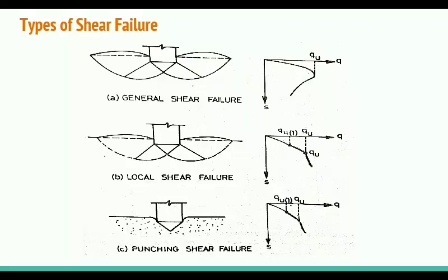In this case, the failure surface does not extend up to the ground surface. This happens when you apply the load on loose sand or soft clay. The failure surface cannot extend up to the ground surface. You will only see the foundation sinking into the soil. There is only a vertical movement.